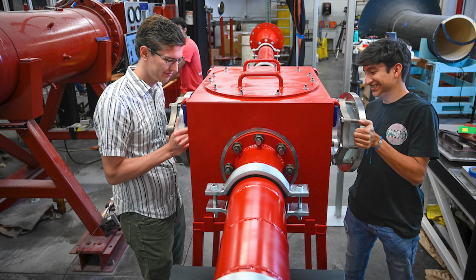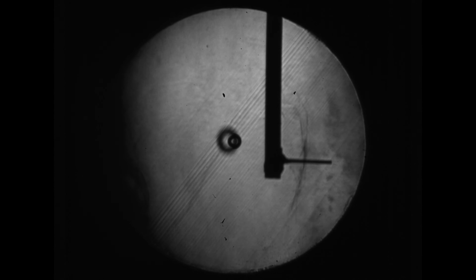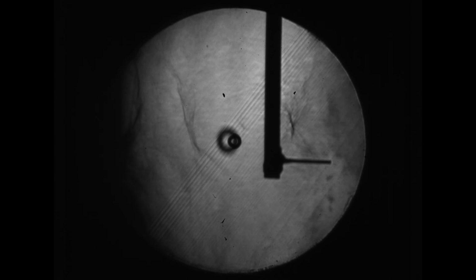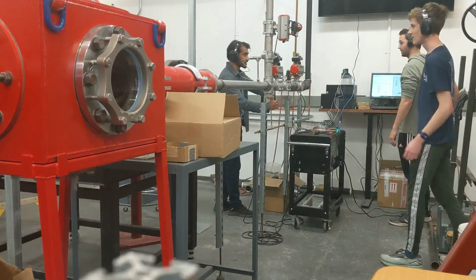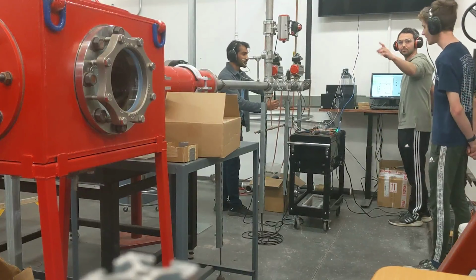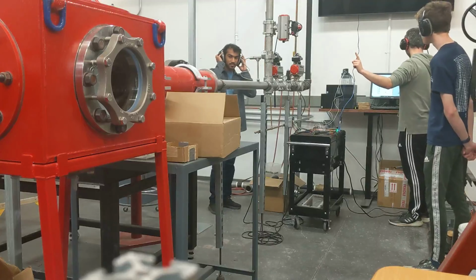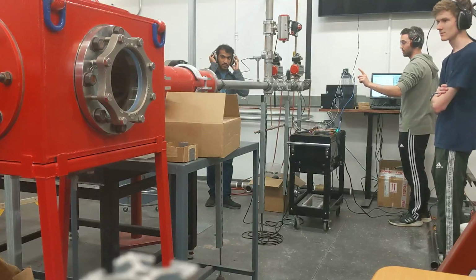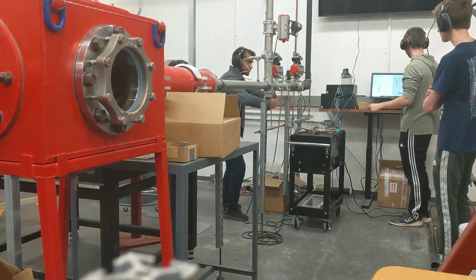As far as processing data, we don't just stick something into the wind tunnel, press run, and collect a whole mountain of data that we have to sift through. When we set up an experiment, we try to measure one specific thing. That could be the location of a shock wave, or the surface pressure on our experiment, or the velocity and which direction it is going, or the shear stress, skin friction on our model. Most of our time is spent setting up the experiment, tweaking it, trying it out, looking at what happened, and then redoing it if needed.